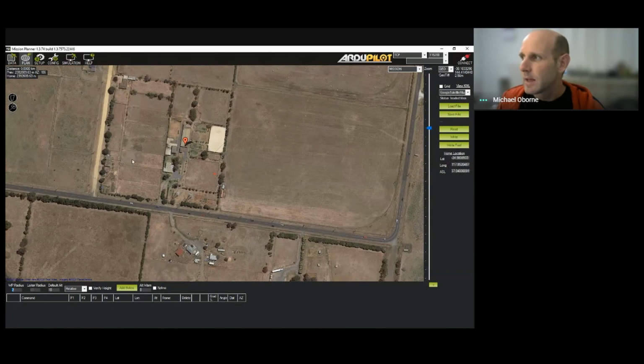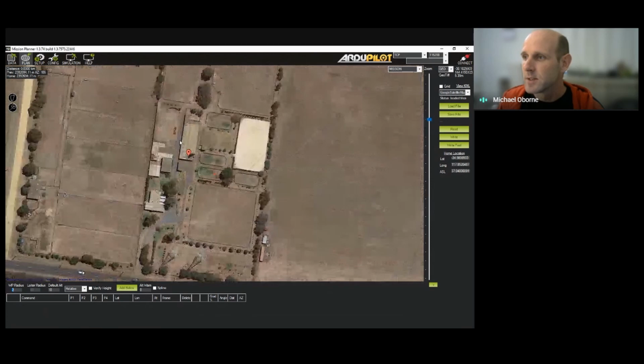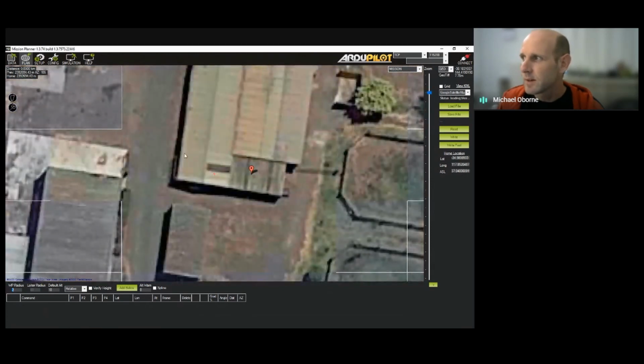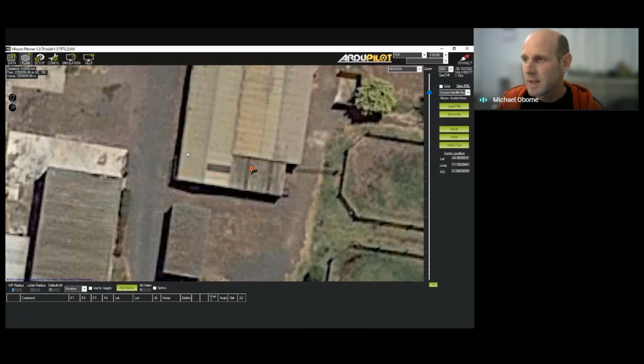But if it's loaded already, when I move over here, you can now see that it says GeoTIFF. So when we did move that GeoTIFF into that DEM directory, it actually loads it to DEM. As I move my mouse out across the edge, it switches back to SRTM and back to GeoTIFF as I move it around. So as I actually look here, it jumps from 7 meters just there down to 5 meters just there, which is actually pretty accurate.